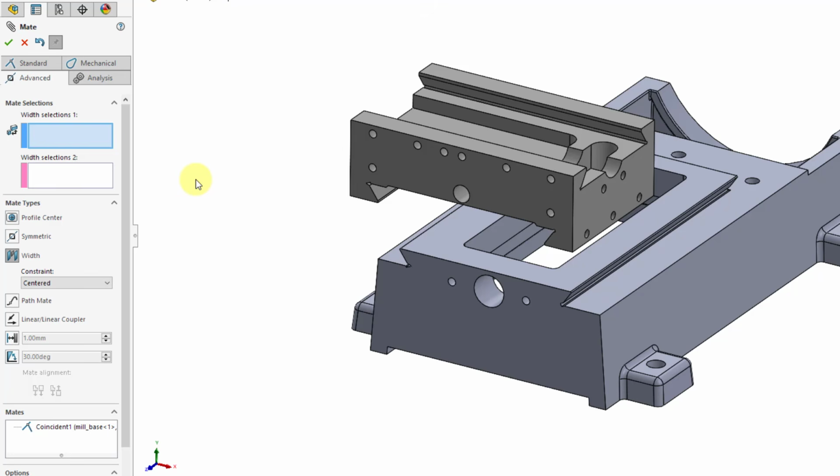And so this is one of the things that people who use SolidWorks really like about SolidWorks, because it saves the trouble of creating datum planes or putting datum planes in the middle in order to add constraints like coincident between those different datum planes.